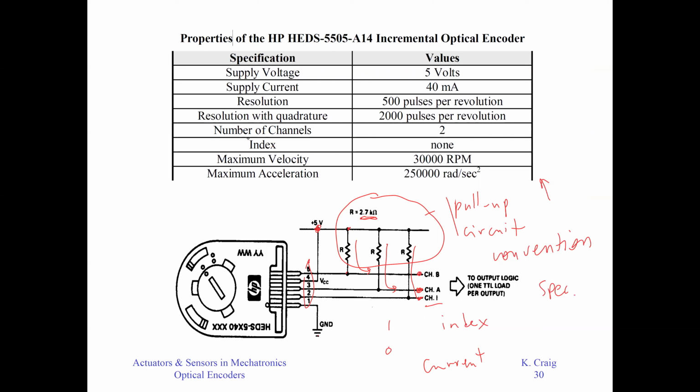So this is used in digital control, especially in TTL logic, transistor logic. It's widely used. If you don't have this one, is it okay? Maybe still okay. But with this one, we'll make all your circuits more reliable, not so much influenced by external disturbances. For the supply voltage, the supply current is about 40 milliamp.